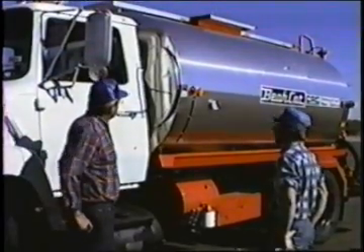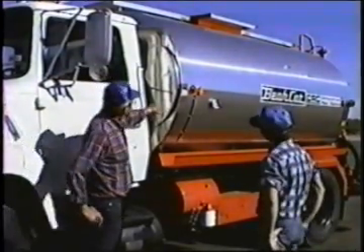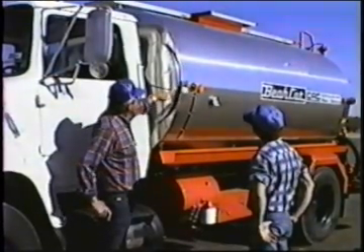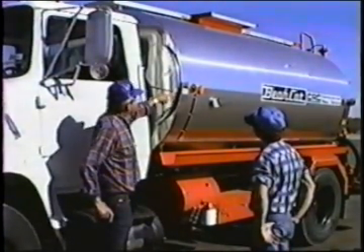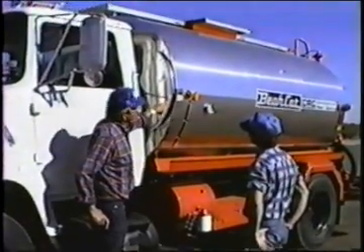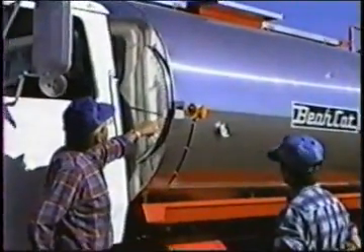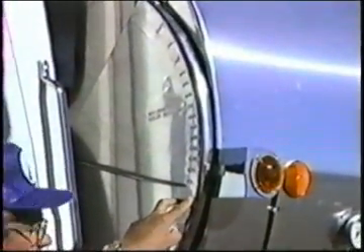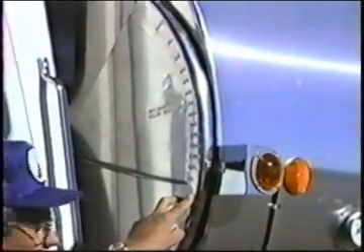Here on the front corner of the tank, Bill, is the float gauge. This shows the amount of liquid in the tank. Right now it's reading 1,450 gallons. It's just marked every 100 gallons, and you just have to interpolate in between. Don't attempt to read it down to 10 gallons. If you get down to that kind of numbers, you're reading numbers that it can't be that accurate on.